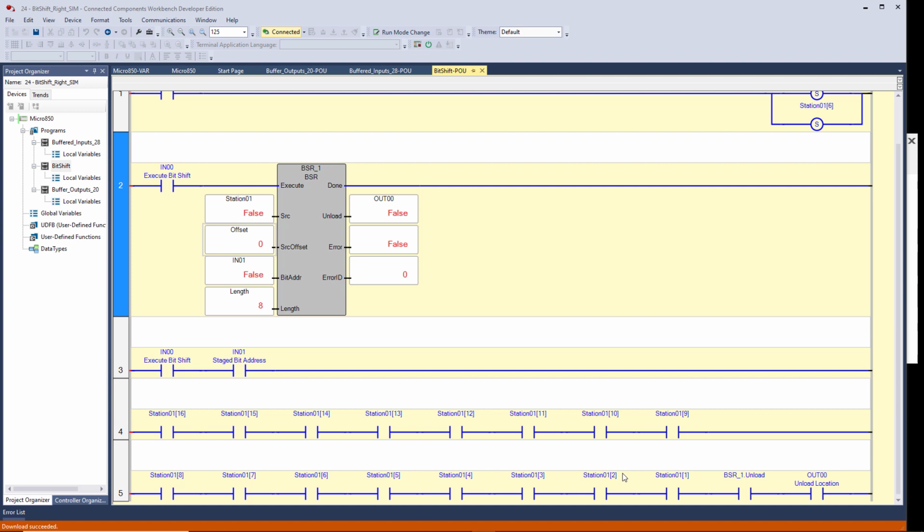Now, when I added my, if you want to call it HMI rungs here, in other words, I'm showing true if on instructions, and I'm looking at bit or element 1 through 8 and 9 through 16. I could have had 1 up here and 16 down here, and then they would have been going in the wrong direction if you're thinking to the right or the left. This way they're going towards the least significant, which is towards the right. So this way is right, going from 8, 7, 6, and so forth. That's moving to the right. Left would be going from 1 to 2 to 3 to 4, as you see it on the screen.